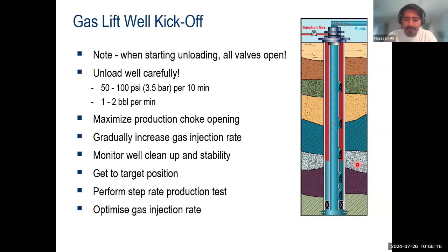Very good question. The size of the valve is determined by many factors. One of the factors that we need to consider is the size of the tubing and the size of the casing. If I show you over here, this is the tubing and this is the casing. And if you see, the valve is on the side, and there is not a lot of space left between this valve and the casing. So one of the considerations is definitely the space available for the valve. The other one is how much you are injecting.